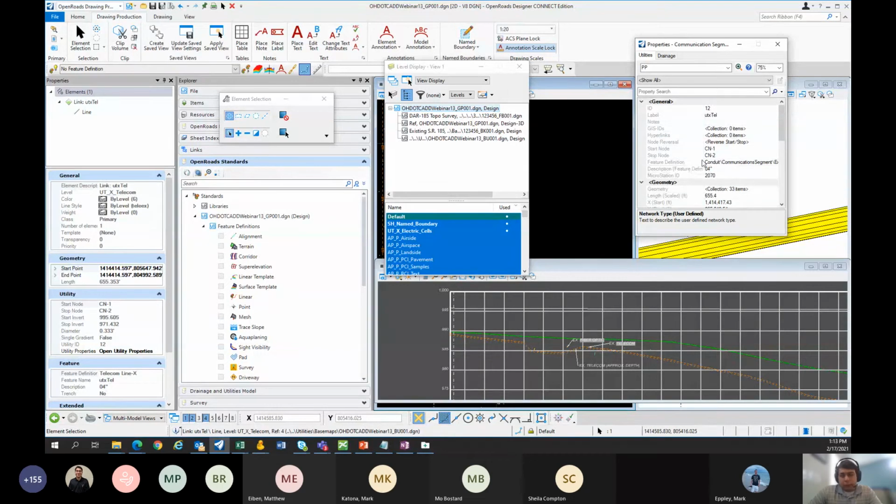Now with the drainage and utility stuff, if you remember how I set those up, I actually used, I think it was the nodes, if I remember right. But the problem with the utilities is I can't predefine that because utilities don't define a prototype. So I had to use some other property because it was really nice using the notes like that, because you could easily bulk edit them with like a flex table or things like that. But when it came to utilities, you can't default a prototype, so you can't default that value. So I had to go down and I just used that, which is better than what they had.